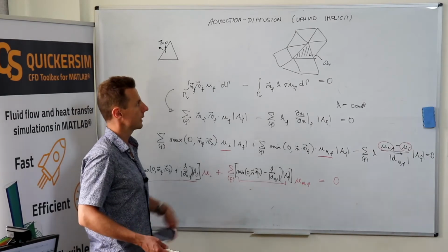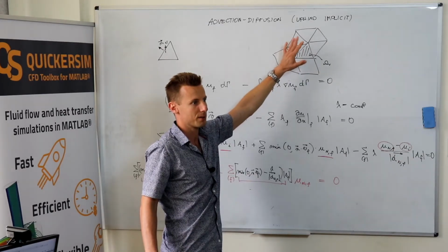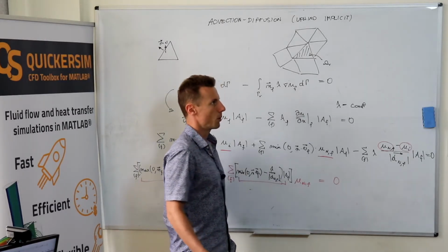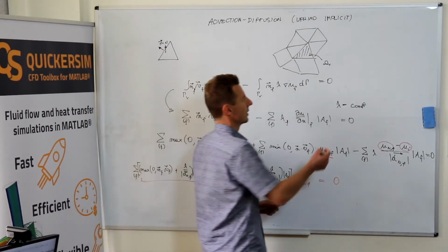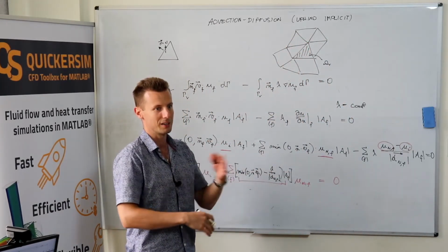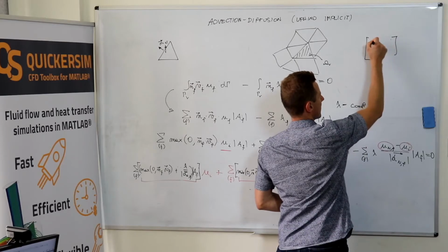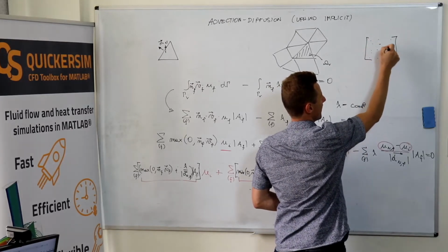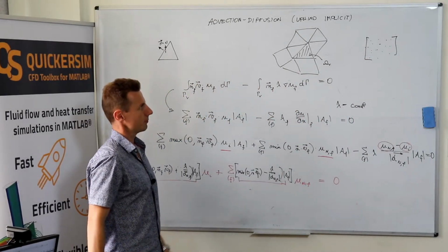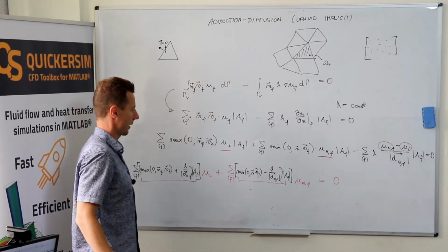About the structure, if you're dealing with unstructured meshes, you will not observe any special sparsity pattern. You will not see that it's block diagonal or something like that, because your nodes and your cells are numbered in an arbitrary order. So what you would see in this sparsity pattern is probably something sparse, but not really. The entries are not gathered across some diagonal or something like that.